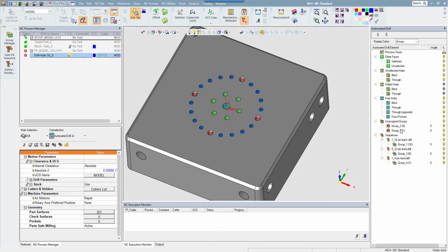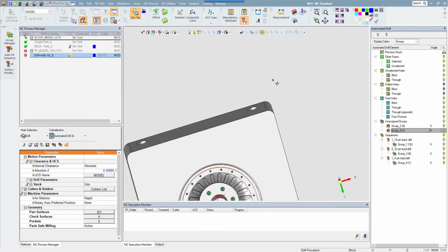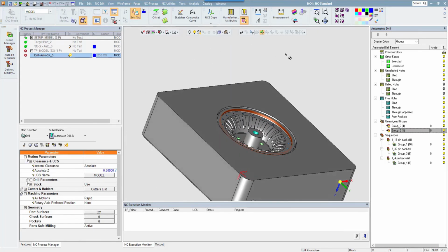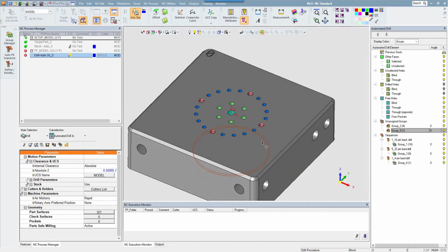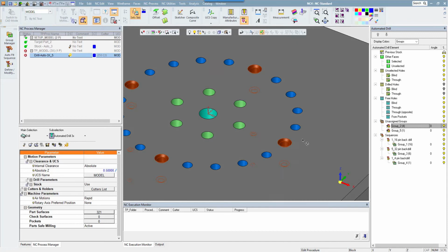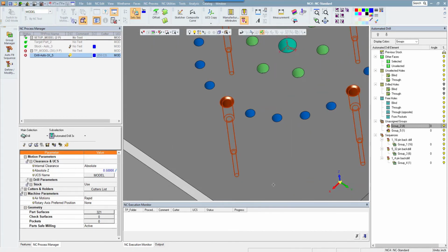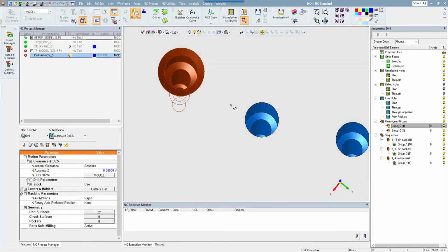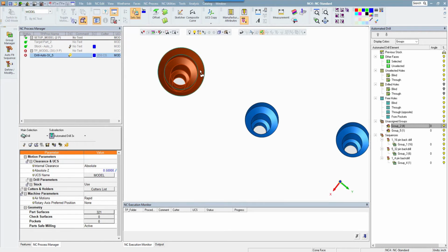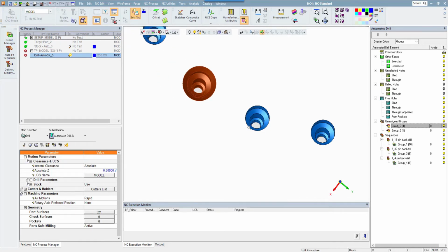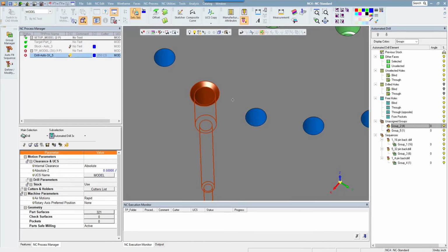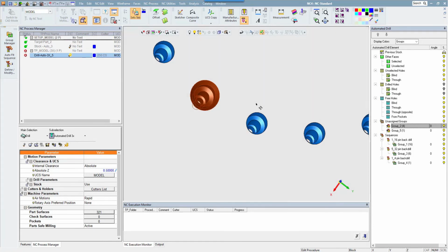So if we go to here, this is the ring on the other side, which isn't really a hole we would do anything with in auto drill. The other one are these 4 holes right here. Now, this is where we find some folks get a little confused or frustrated because this hole is the same as this hole. There's just a chamfer on it. So it's technically not a breach. It's not a partial interruption. That chamfer goes all the way around. It makes it different geometry.